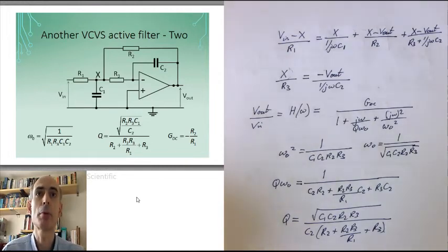One technique is perhaps to pick values of R1, R3, C1 and C2 to give you the resonant frequency that you want, and then pick R2 to give you the value of the gain that you want, since the resonant frequency is not a function of R2, and then to get the Q factor to change the ratio of C1 and C2 while leaving their product the same.